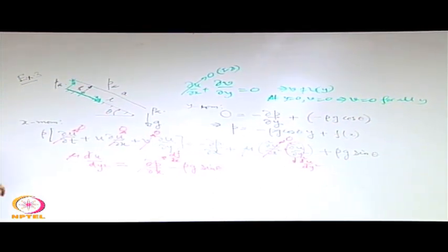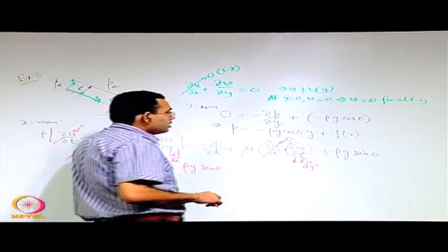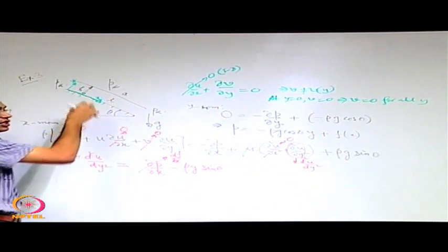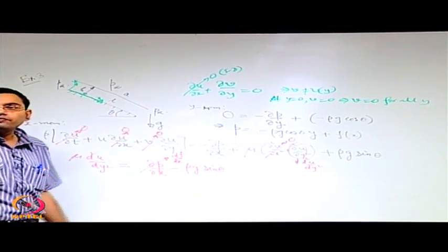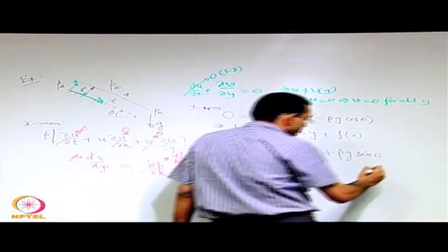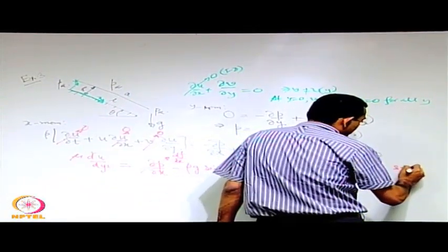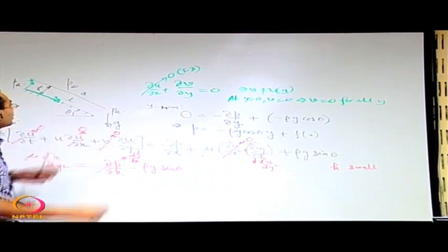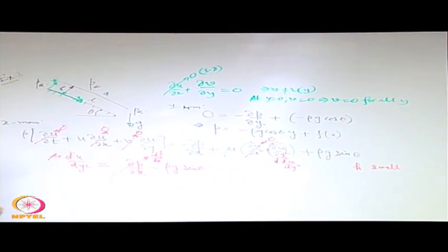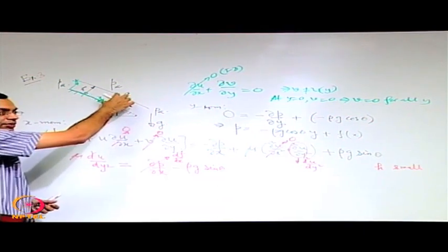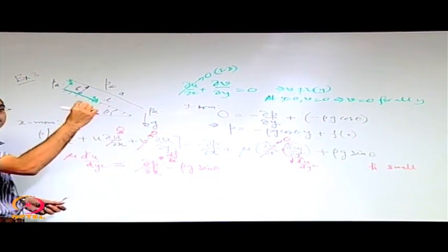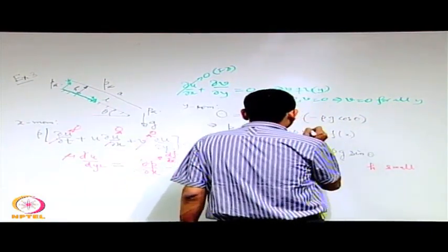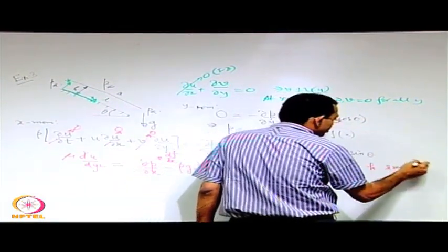Now one important assumption is that the gap h is very small, so that we call it a thin film. So if h is small, what is an important consequence? The effect of the body force along the y direction is not important, because of the very thin gap. The effect of gravity within a thin gap is not important. So because h is small, this particular effect is small.